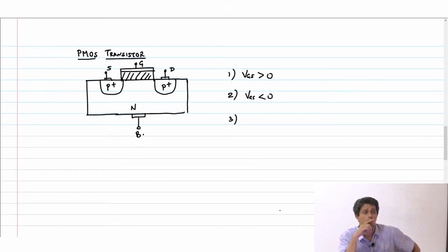You will attract positive charges here, right? And therefore you will get negative charges out here, right? Enough number of electrons and so on, you will get negative charges there, which is again not very useful, and therefore this region is what you are basically accumulating more electrons at the surface than what is there in the bulk, and therefore this region now is called accumulation.